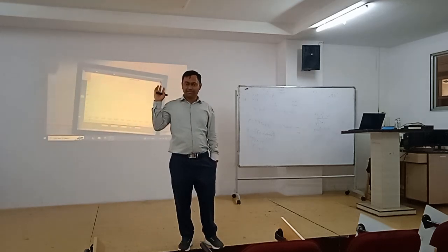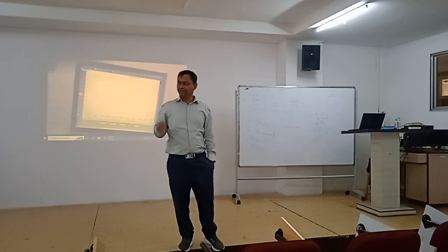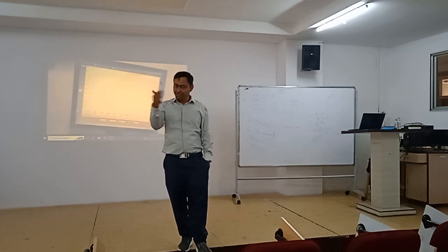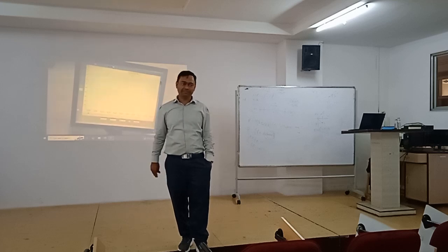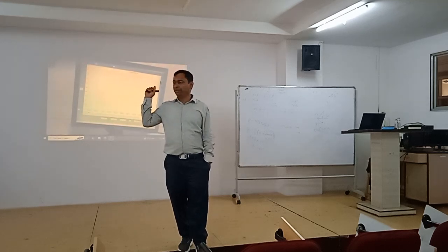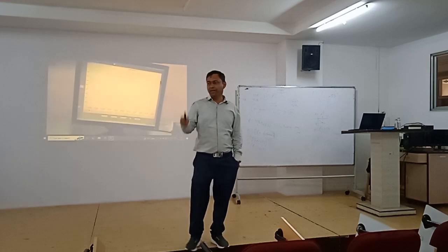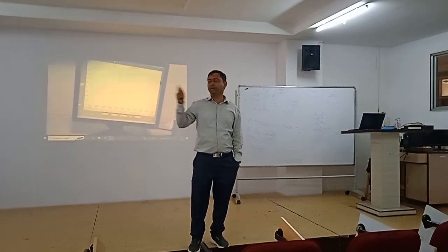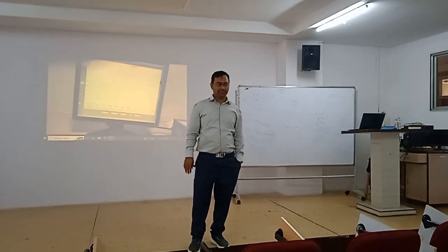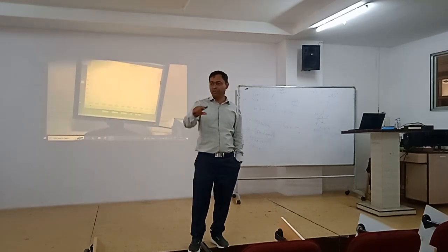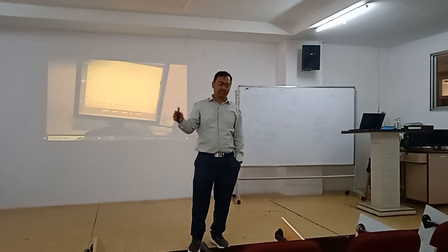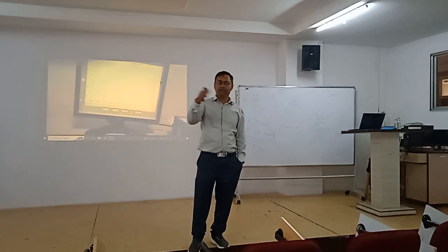So, do you think it's simple? It seems to be simple, but ten years ago it was not simple. Why? Because we are using an induction motor, and an induction motor is considered to be a constant speed machine. Correct? Speed variation you can achieve only by varying the voltage and some other strategies, but not the way we achieve it with DC motors.